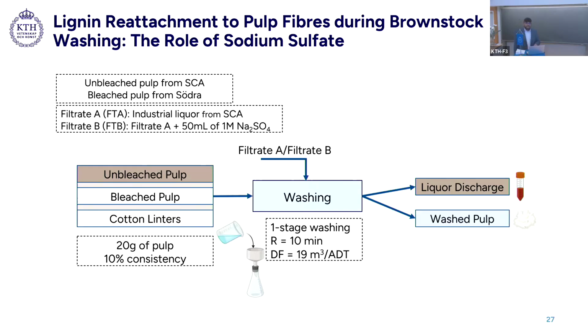The washing performed was 1-stage washing with a residence time of 10 minutes and a dilution factor of 19, performed in a lab in a Buchner funnel.